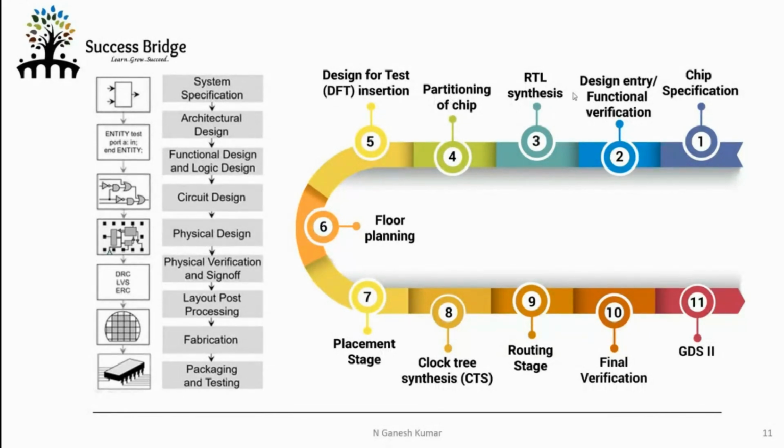Now DFT plays a middle role, where you take this RTL synthesized netlist and start working on it. You insert additional logic, that is DFT logic, and finally you validate it and deliver it to the physical design team again. So DFT and physical design interact with each other throughout the chip designing process. DFT also interacts with RTL. Each working domain in one particular project interacts with the others continuously, but the majority of the exchange happens between DFT and PD, because PD can start working only from DFT, since extra logic is added into the existing design that RTL has given.